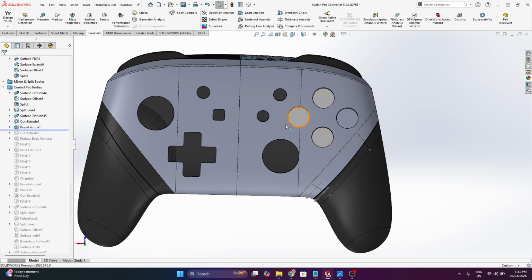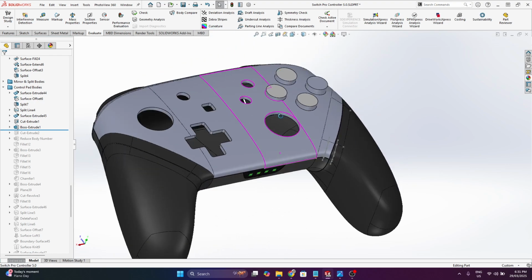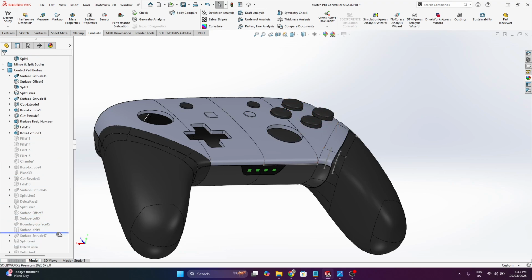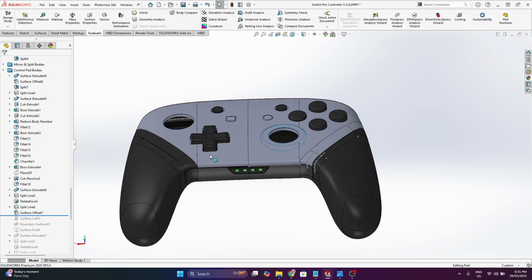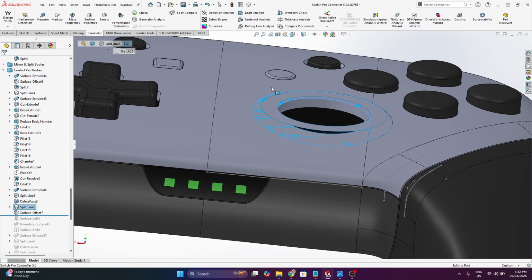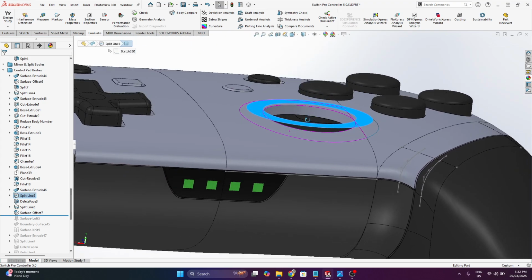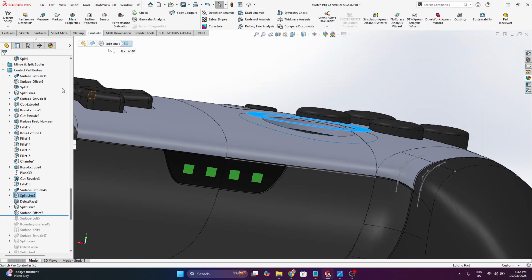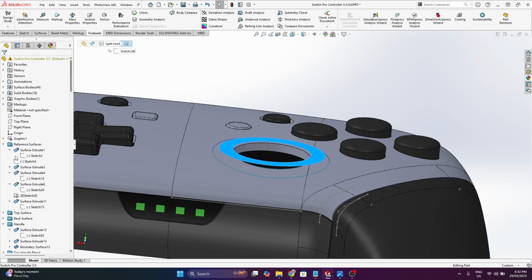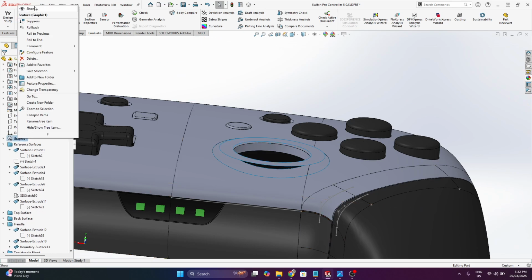Then I started producing solid bodies, and this was relatively simple at this point. Just adding fillets, doing a loft or a blend between where the control pads are. So I produced a flat surface according to my 3D scan.